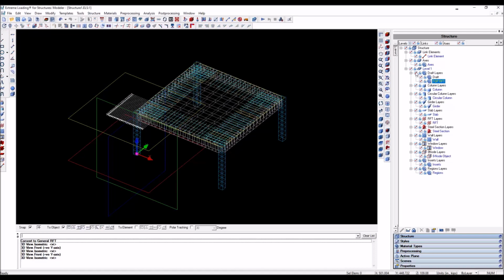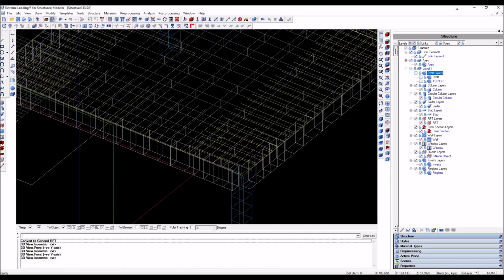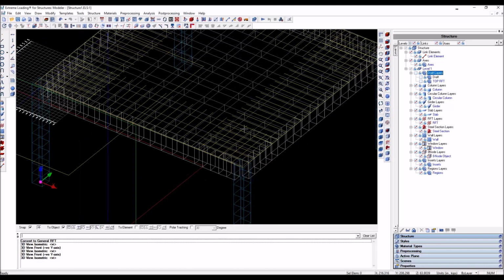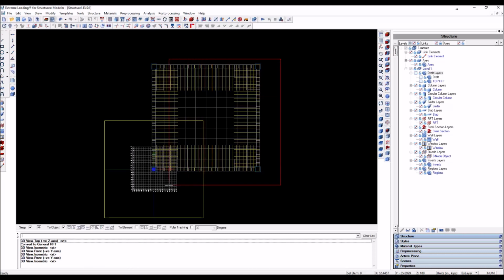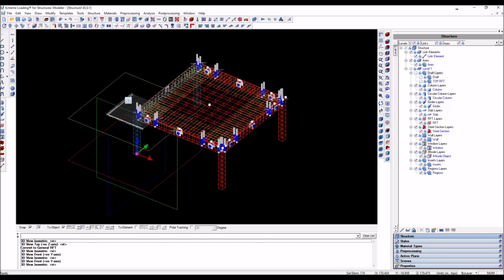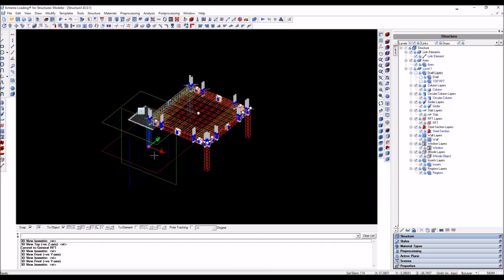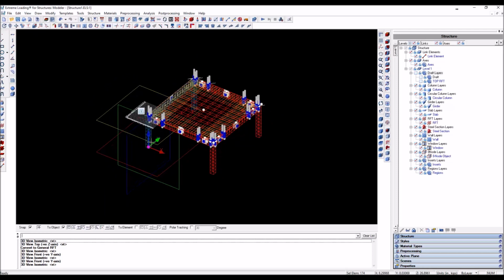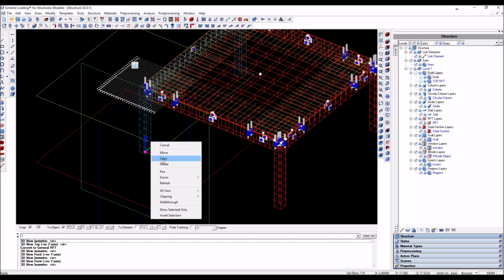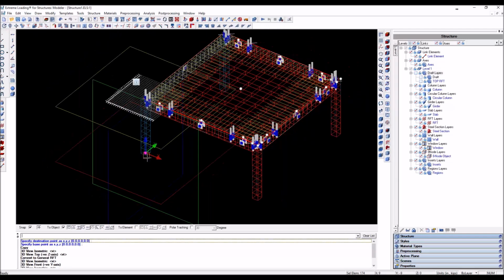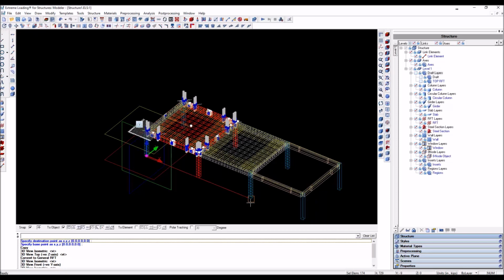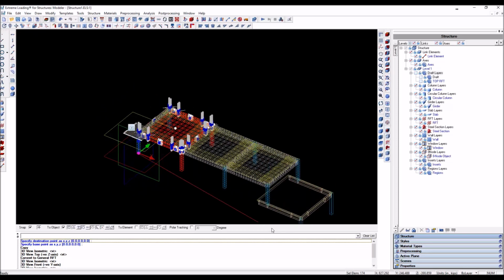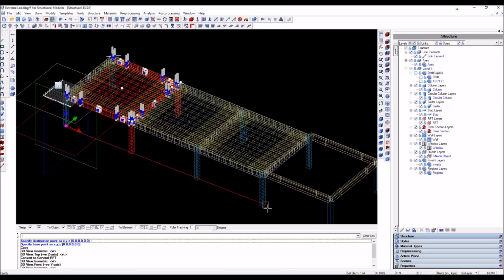Now we can hide all the draft layers and we'll find the reinforcement rebars in place. Now what I need to do is just to make a copy from what we have in here, array it, or use the copy command to create the other base. So I'm going to select the copy command, and I'm going to take copies from this frame, repeat it 5 more times.